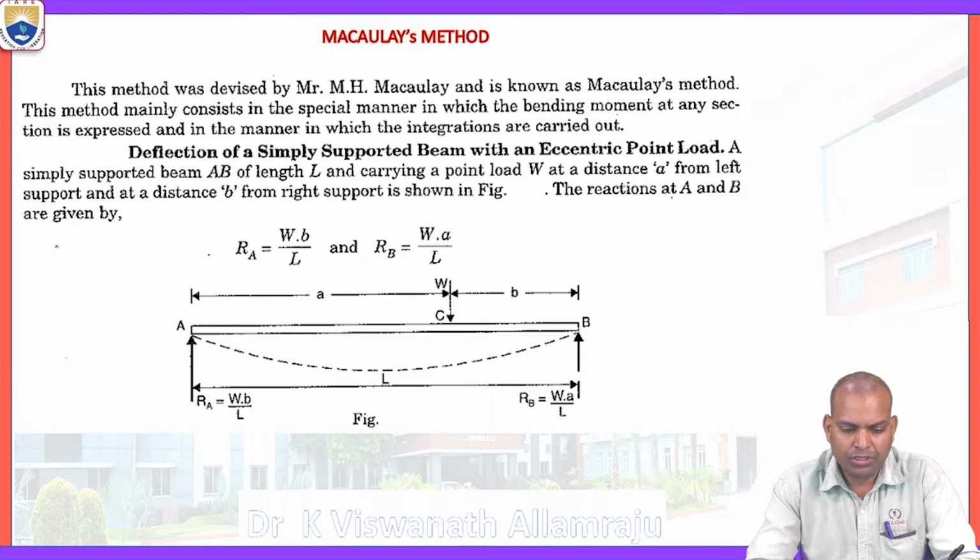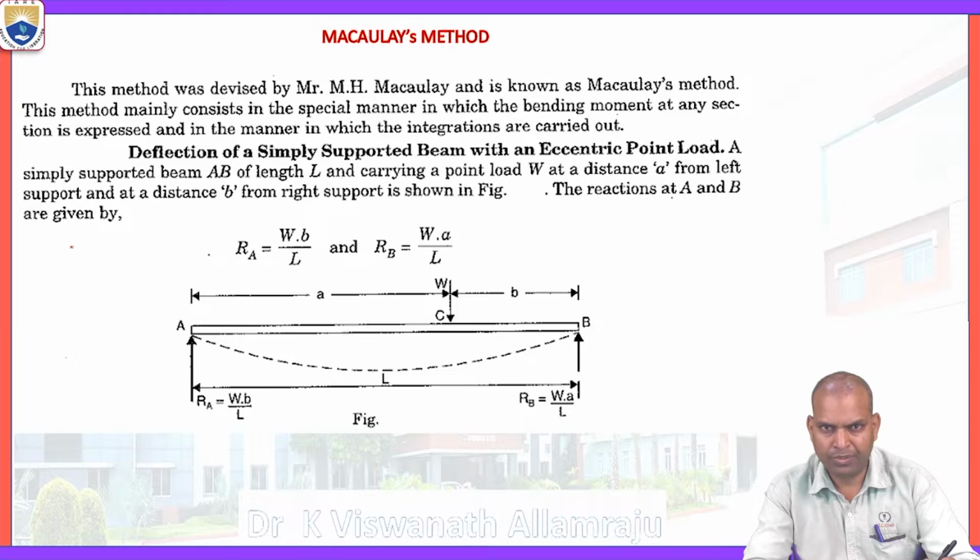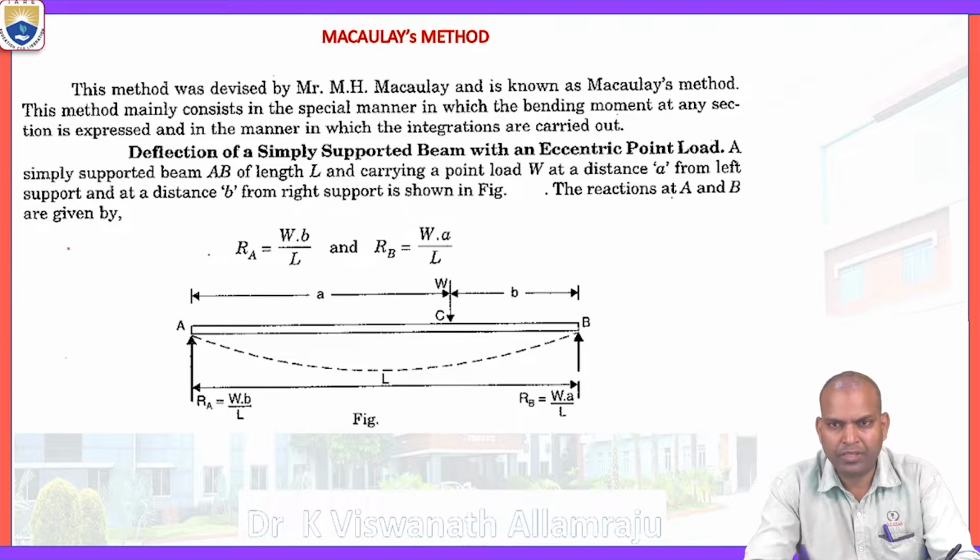But this Macaulay's method is very simple, and it can be understood easily for problems of eccentric loads, uniformly distributed loads, and also a combination of point load and uniformly distributed load, to find slope and deflections along the length of the beam.